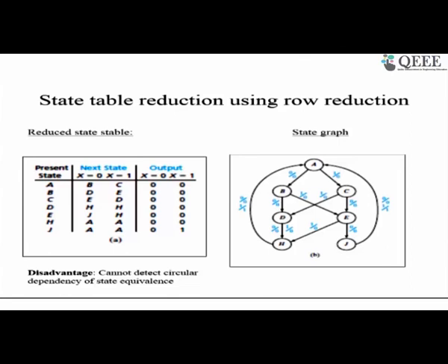So that is how we treat the generic problem and look for designing a sequence detector. Can we design and synthesize the circuit with the help of the standard sequential machine model? Yes, if there is a sequential circuit to be designed, you can always view it as a finite state machine and follow the same procedure that we have encountered. That is, come up with the state graph, then come up with the state table, use a good state assignment, and then realize it using either D or T or JK flip flop.